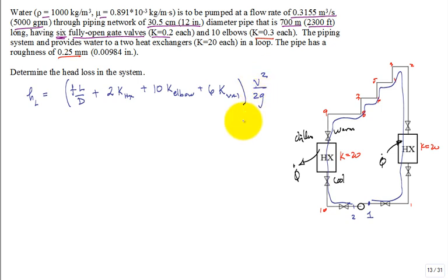Now, if the diameter changes, then the mean velocity or average velocity through these components, or the characterizing velocity that characterizes the head loss, which is sometimes the inlet velocity or the average velocity through the device, if the area of the pipe is changing, then I have to play with some area ratios. Okay, but everything says that the pipe diameter stays the same throughout the whole system, so I'm not adjusting for that. Does this equation look reasonable? Yeah.